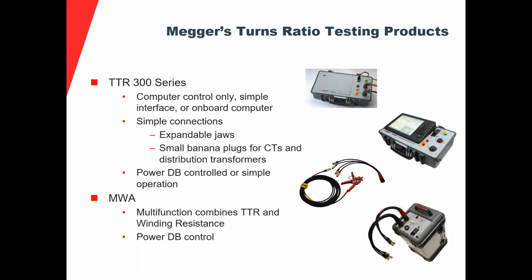You take all the cables up on top of the transformer. You make all your connections. And then you drop down your lines and make your connection down at the ground versus having all your cords and your umbilical cord all connected in one. This is going to help you with troubleshooting. It's going to help you with, if you don't need to use that phase, you don't have to connect it, things like that. As well as that, the jaw is expandable.